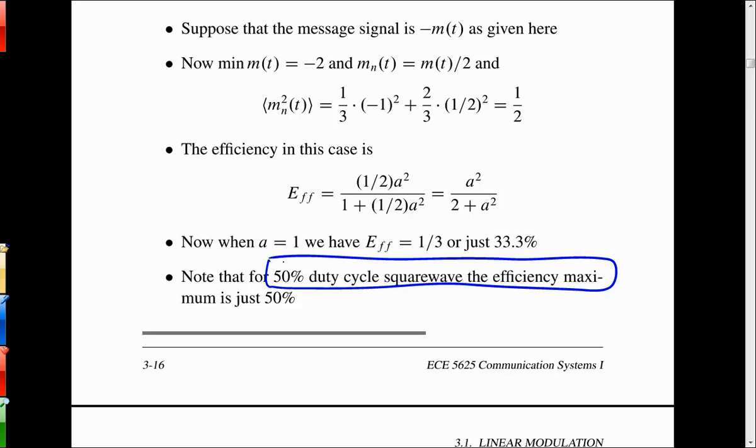So with like a 70% duty cycle, is it linear? So like 70% duty cycle would be 70, or not? But not 70. Well, you can see for the pulse train what this equation has in it. This is for 33% duty cycle. Oh, okay. But yeah, you can approach 100% efficiency for this one.